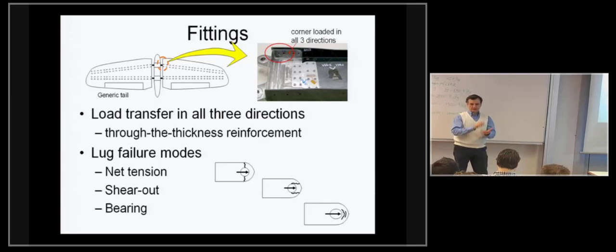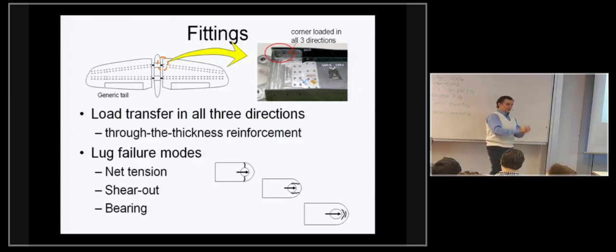For a composite structure, that's a very important challenge, if not a problem, because the out-of-plane strength of the matrix used is so small that it makes it very difficult to design the structure without making it very heavy. Or if you decide, for example, to use fasteners or stitching to hold everything together, you make it very expensive.